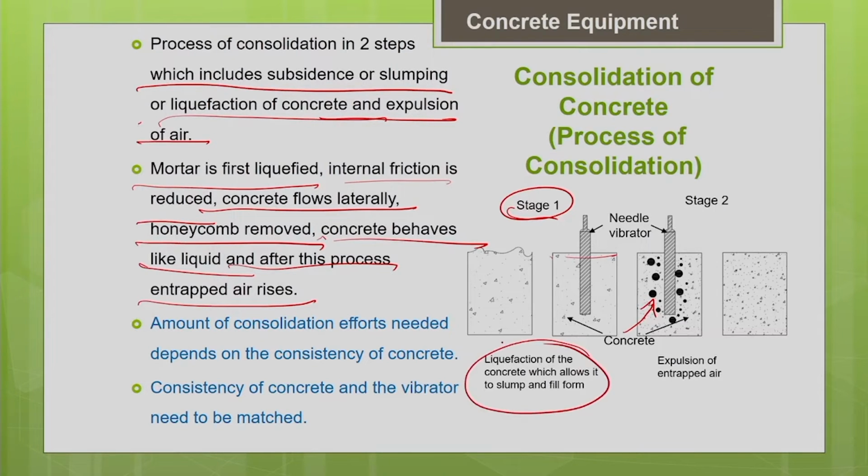The concrete gets liquefied due to the vibration action. This liquefaction will allow it to slump and fill the form completely. Because of that, your entrapped air will rise to the surface. That is what is happening in the second stage.